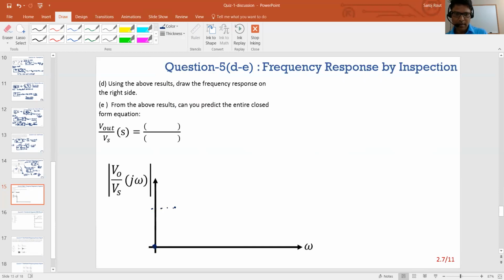And then let's say this is the point where the transfer function is equal to 1. So at infinity, it is 1. And let's say this was a linear plot, I mean, linear axis, not log scale. It just somehow linearly goes and joins. And we found out that this halfway point, so let's say this is half, is at 1 over RC. So that's your Bode plot. So it's a high pass filter with a pole at 1 over RC.